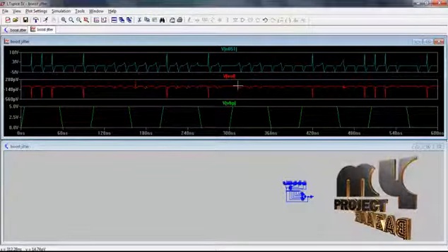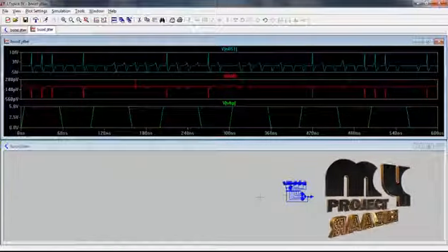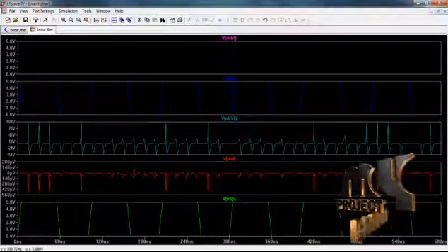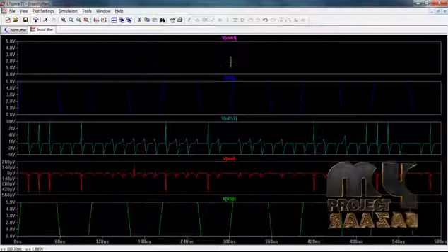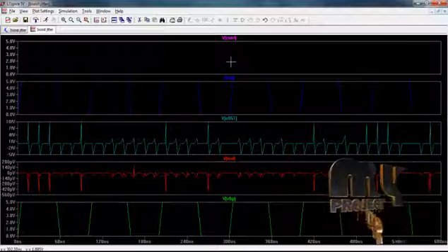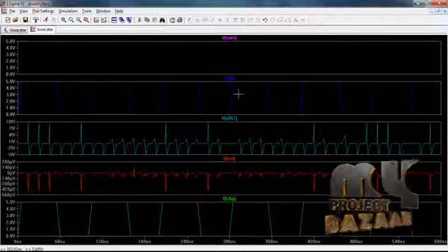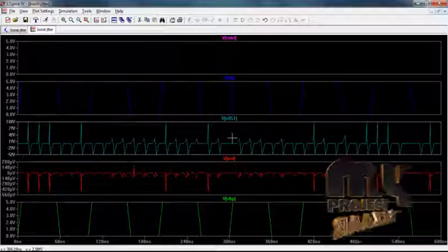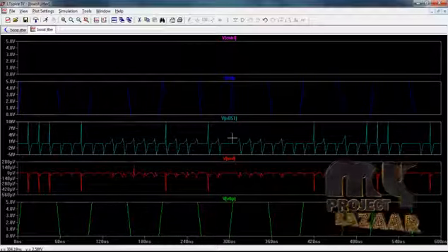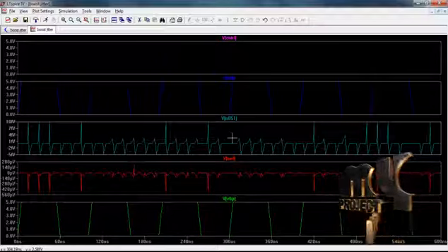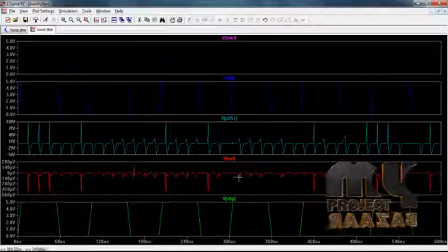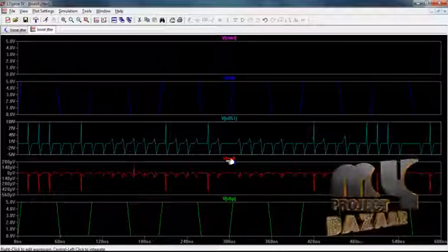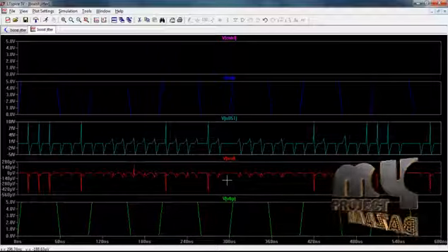Now we are going to fully explain these waveforms. This is the final output waveforms for our product. VBB is an input signal. V control is a control signal of a switch. VS0 is a selection bit of the switching blocks. This is an output of the frequency divider. This frequency divider output is further directly applied to the D flip-flop. They will produce the final output waveform. Vout is the final output waveform of our product.